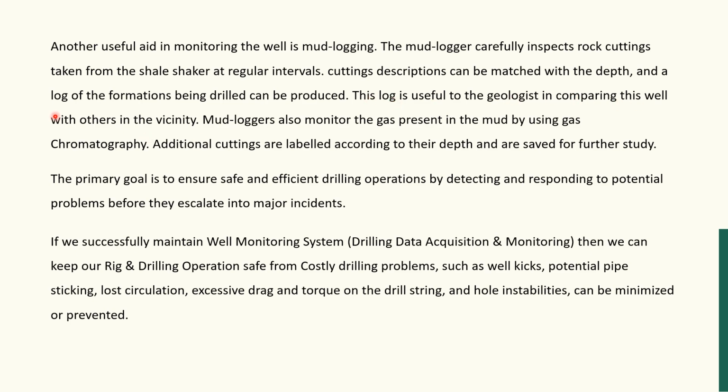The mud logger takes the drill cuttings from the shale shaker, examines them, and maintains a log of the results of that examination. This log is useful to the geologist in comparing this well with others in the vicinity. If in future any other well is researched or surveyed, these cuttings will help the geologist. The mud loggers also monitor the gas present in the mud by using gas chromatography.